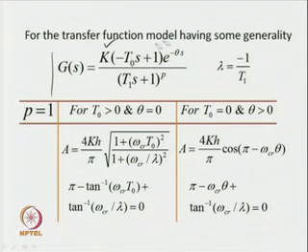Then for various values of P, we get different types of transfer function models, and similarly for various values of theta and T0, it is possible to get transfer function models with time delay and transfer function models with non-minimum phase characteristics. Now, when lambda is assumed as lambda equal to minus 1 upon T1, when P is equal to 1, for the case T0 is greater than 0 and theta equal to 0, theta equal to 0 means we basically get the non-minimum phase transfer function models.